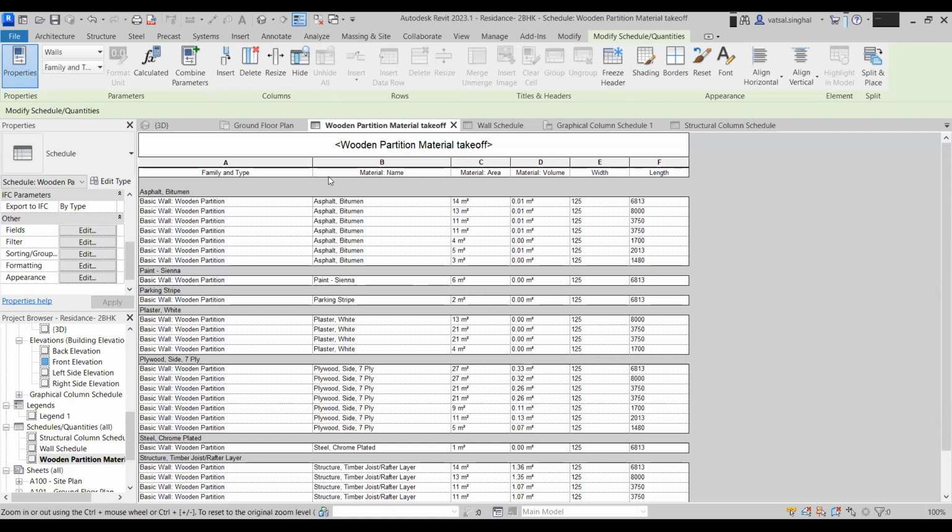These schedules, you can just take them to the sheet here in Revit, but for Excel, you want to generate a BOQ or anything, so for that you need to link it to Excel. So that will now be explained, how you can link directly through Dynamo to Excel. Dynamo is also a part of Revit, a software here in Revit only. So he'll take things forward now. Over to Varun. Thank you.